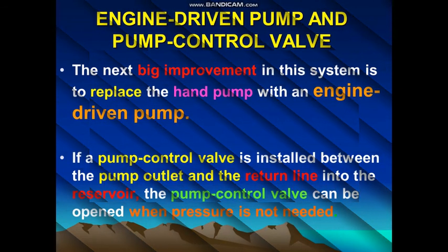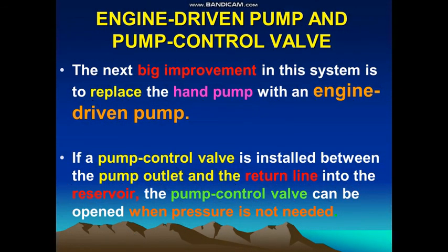Now we will talk about some components of the hydraulic system, and I will start with the engine driven pump and pump control valve. The next big improvement in this system is to replace the hand pump with an engine-driven pump. That means when the engine starts, the hydraulic system pump will start working. If a pump control valve is installed between the pump outlet and the return line into the reservoir, the pump control valve can be opened when the pressure is not needed.